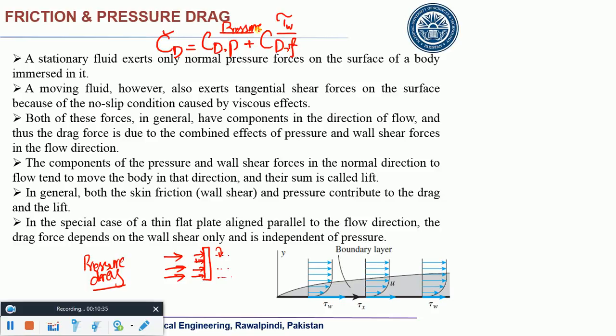Just look at that stuff. Is it the pressure component which is dominant in case of flow over a flat plate or an airfoil or a wing, or is it the friction? It is the shear part, which is the friction coefficient. Why? Because they are thin bodies. If they are thin bodies, pressure difference would not play any dominant role in creating the major drag component. So if you consider a bluff body, just like a cylinder and a ball, for example, what would be the dominant component? Is it the friction part or is it the pressure part?